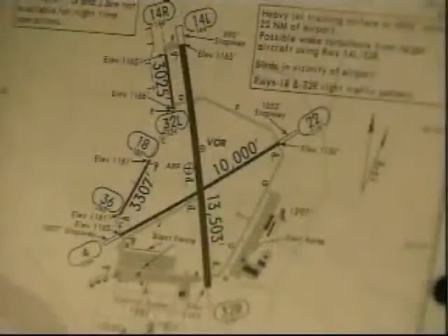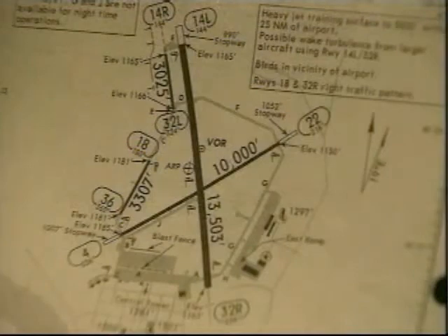It looks like air traffic is landing on both runways, 32 right and runway 22. The wind is 280 degrees at 25 knots. Both runways are dry. So if ATC offers us an option to land on runway 22, we won't accept it. We'll stick with runway 32 right as we discussed because it's a better runway. Any questions?